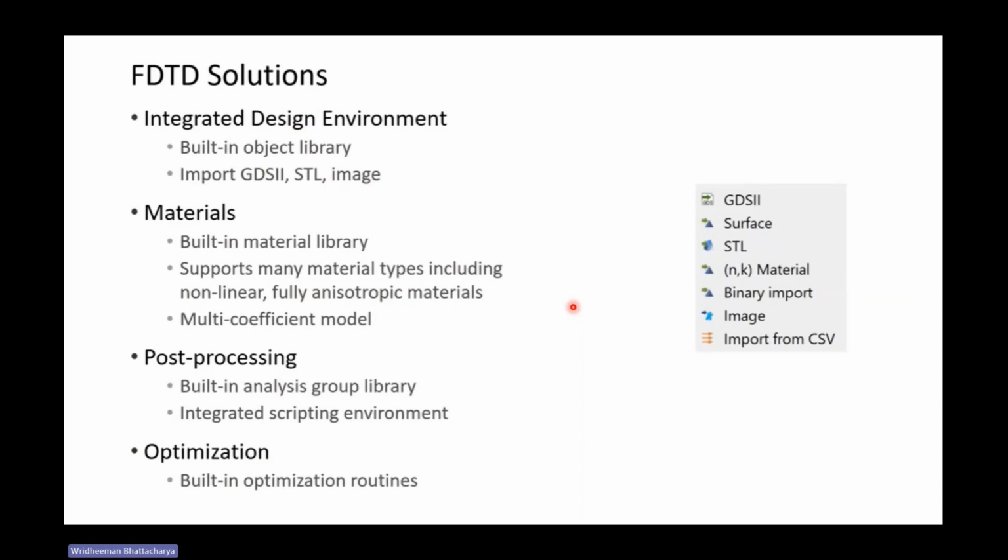The surface we could design on our own, or we could include it from CAD, 3D CAD libraries, or AutoCAD files. And we can also import the GDS files. Lumerical also offers exporting the design directly to KLayout, while it also offers to import the GDS files.